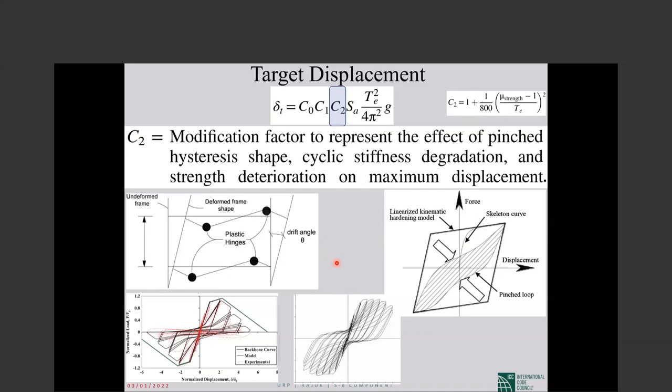That's why a building that has a larger period is less affected compared to a building that has a smaller period.